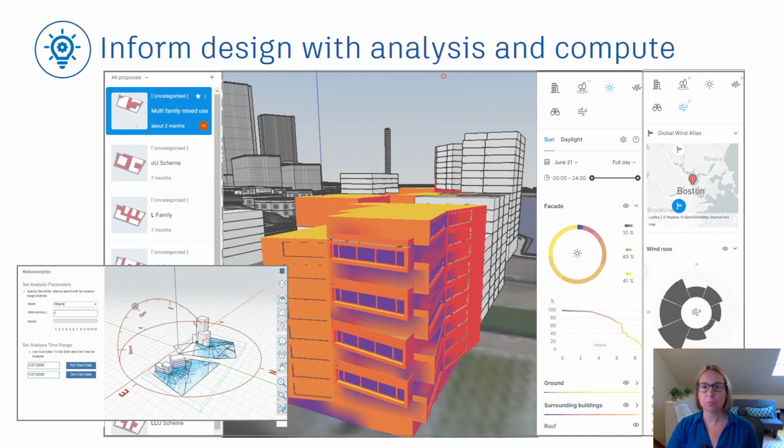We'll do this by exposing more of FormIt's JavaScript API as Dynamo nodes so that design technologists can create custom graphs for project-specific needs. For example, the image in the bottom left shows a custom plugin built to track shadows across a site. The time intervals are customizable, so shadows can be tracked hourly across a day, or across a month or a year. As we expose more of the API through Dynamo nodes, more design technologists can take advantage of FormIt and Dynamo to customize their analysis needs.